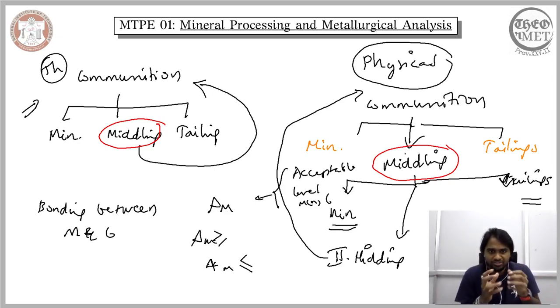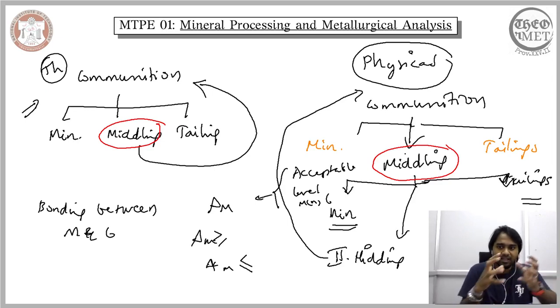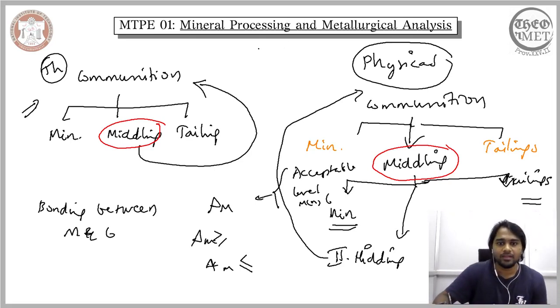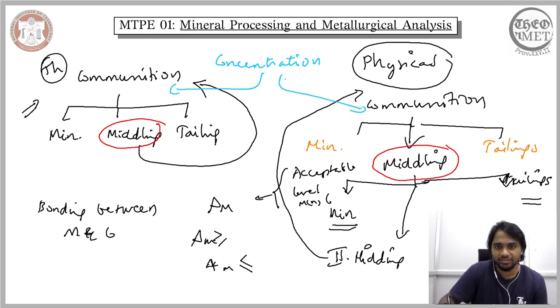Now we saw that comminution breaks down the larger particles into smaller particles. Even though this liberates to some degree the locked-in mineral from its gangue, these fragments will be helpful to us only when we are able to separate the middlings, the mineral particles and the tailing particles. We can perform any further operation on the smaller fragments only when we are able to separate all these different categories of particles. This separation is what we refer to as concentration. All the while we were talking about liberation, concentration was implicitly involved here, here and also here.